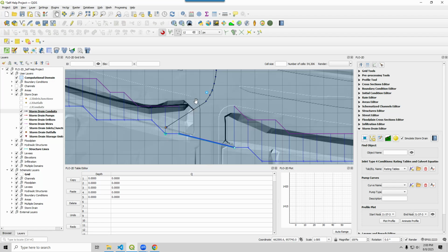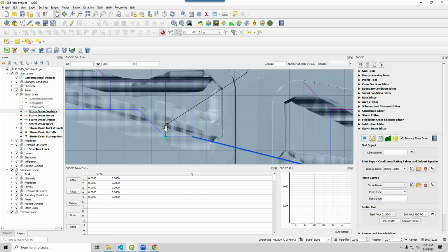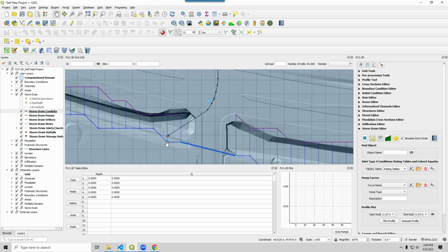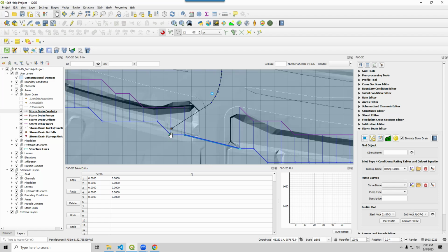Now we are not applying our outfall to the bank. We are applying it to the cross section. And so we want it to stay away from other features. So we keep it away from the hydraulic structure, the culvert, and put it one node downstream of the culvert and make sure it's assigned to the left bank. And this one's barely making it. It's right on the edge, but as long as the green node shows you that that's right inside there, then that does not matter. Because this outfall is interfacing to the channel cross section.